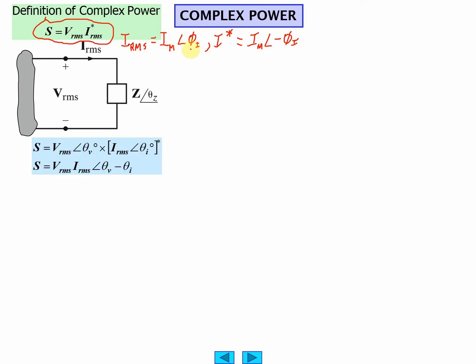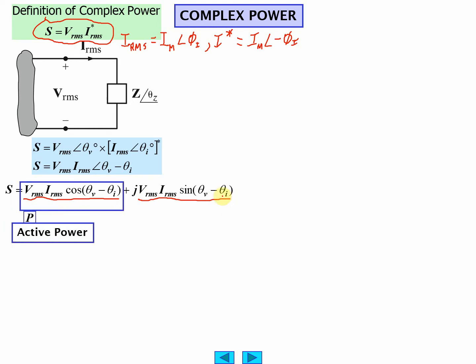Okay, so moving along, the power can be written like this, V I star. Since for the complex conjugate you just negate the angle, it becomes the difference of the angles. And just using Euler's identity, we get this expression. The magnitudes times the power factor. That's the apparent power, that's the real power, and this is the reactive power. Active, reactive. They use the symbols P and Q.